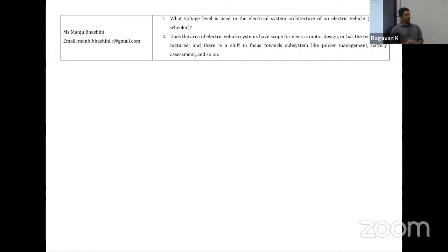So that's my thought. But I would say at this point, if you combine things like thermal management, cooling methods, materials for the laminations, and the winding methods, motors definitely have tremendous potential, in particular in manufacturing, because we still don't do it well. Most of our motors are still coming as a Frankenstein system. We get pieces from elsewhere. So if you can create a localized opportunity for building your motor and also keep your supply chain disruption minimal, you might have a very strong case. Switch reluctance machine, that was one of the selling points. It's only copper and steel, so it works. But if you go further and start talking about Hiperco 50, all of a sudden your alloys change, and it gets a little more complicated there.